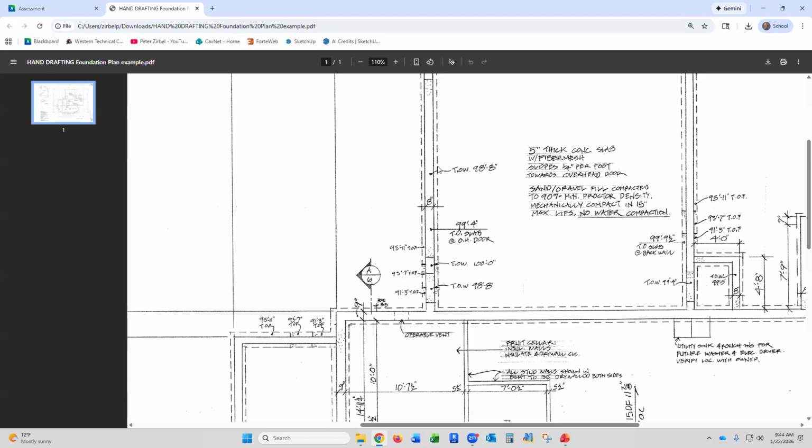So let me just sketch that up here. So if I had my wall at the same height as my slab, there's a gap here. We don't want that. So what they typically do is they drop this top of wall wherever there's a door opening. And they pour it like that so that when you're driving out, you don't see the crack where the wall hits the slab. That slab overlaps the wall. Those of you in construction, nod your head, because that's the way they do it.